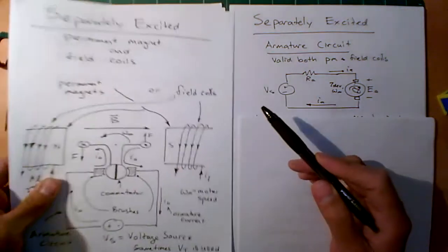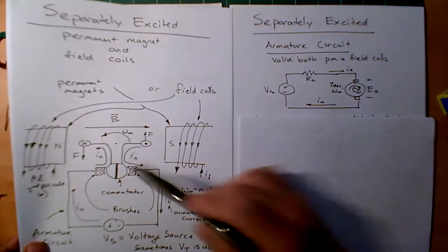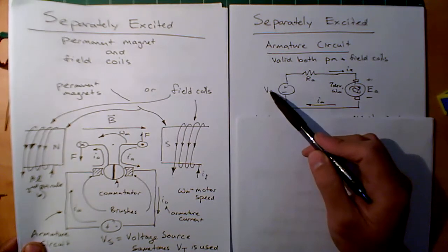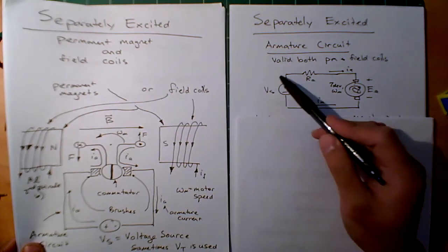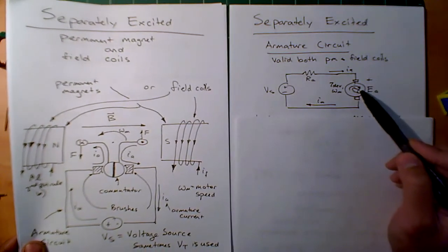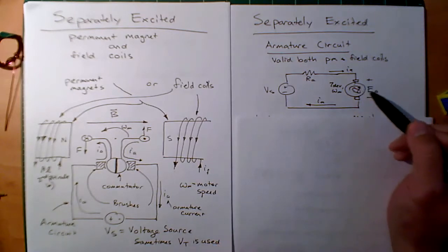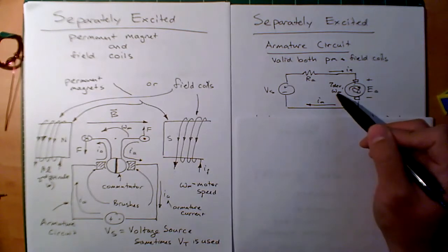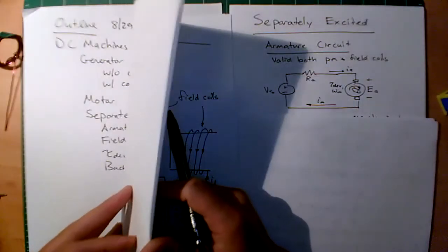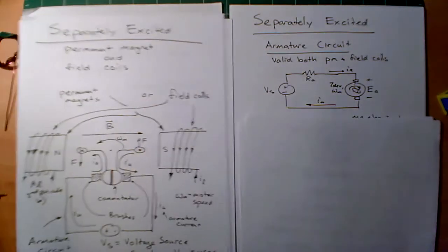So it is an unfortunate thing that when you want to run it as a motor, you still generate this voltage. It's a voltage that's smaller than this under normal motoring circumstances in such a way that current flows, but it's there nonetheless, right? You cannot make that go away. That's just part of the nature of it, okay? Now, this EA, as your speed picks up more and more, you are going to get more voltage, right? And we saw that, of course, in the Faraday's law equation, right here, more speed, more voltage, okay?